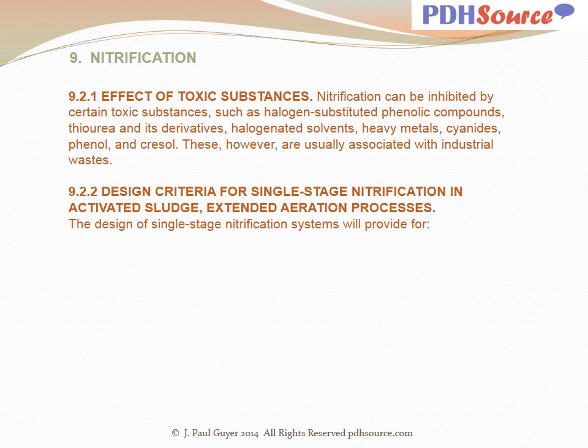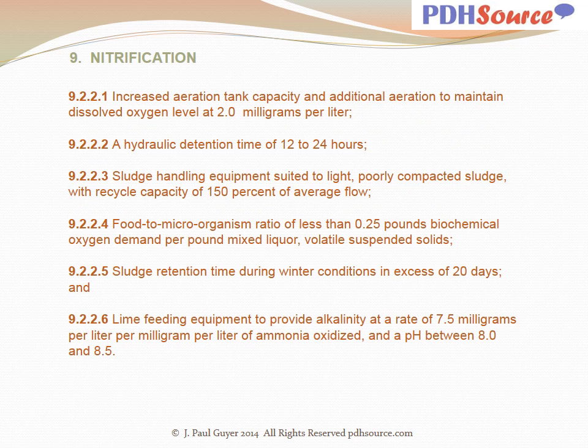The design criteria for single-stage nitrification in activated sludge extended aeration processes will provide for the following. Increased aeration tank capacity and additional aeration to maintain dissolved oxygen level at 2.0 milligrams per liter.